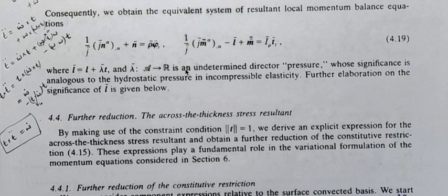When we resolve these equations in terms of components, we have two options: one is the convected basis, and the other is the Cartesian basis or the director orthogonal frame. When we resolve along those frames, what form it takes, and how we are going to combine it in the energy equation and the weak form development, those things we are yet to see.